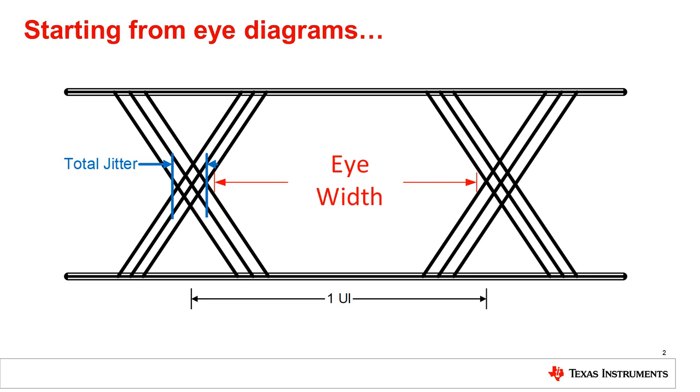Eye diagrams are great when trying to understand how data is affected by a certain channel. However, eye diagrams only show the data quality over a relatively small data sample used to construct the eye diagram. Systems transmitting data with high total jitter and small eye width tend to have poor performance and are more likely to include erroneous bits. The eye opening can be used to extract an estimate for bit error rate, or BER, for the specific eye diagram and form the bathtub curve. For more background on eye diagrams, please refer to our TI Precision Labs video, What is an Eye Diagram?